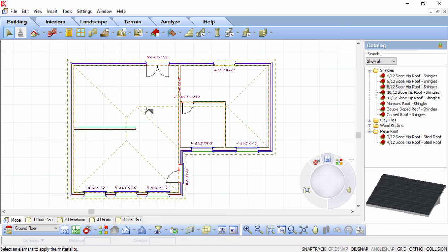Roof surface edges are represented by a dashed line. Once you've inserted a roof, you can edit the properties of each roof segment individually to create a complex roof with varying pitches, styles, and plate heights. For example, you can convert a hip end to a gable end, edit the support height, edit the overhang distance, edit the slope, and control the appearance of fascias, soffits, and gables.